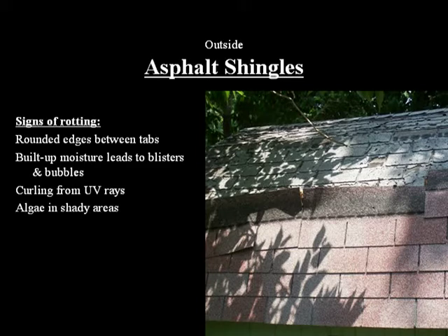Also, be wary of algae growing in shady areas. If algae are not removed, it will eventually rot the shingles. Any of these symptoms should tell you that your roof is leaking or getting ready to leak.